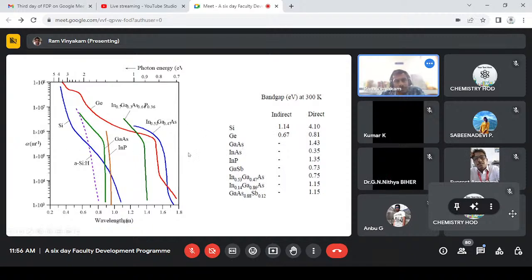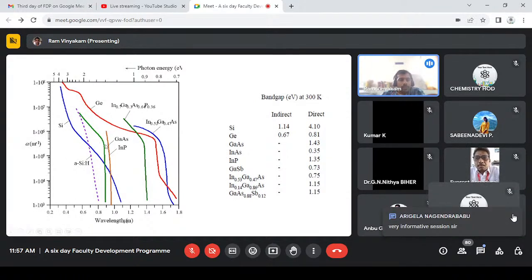So these are the famous detectors up to date, in the case of TV and other devices we use domestically also. Mostly, if you compare photodetectors, germanium is more efficient than silicon. The absorption coefficient will tell why germanium is more efficient than silicon. For wavelengths from 1.8 micron to the higher energy range up to 0.4 micron, germanium will dominate silicon. Even the compound semiconductors have a moderate rate when compared with germanium detectors.